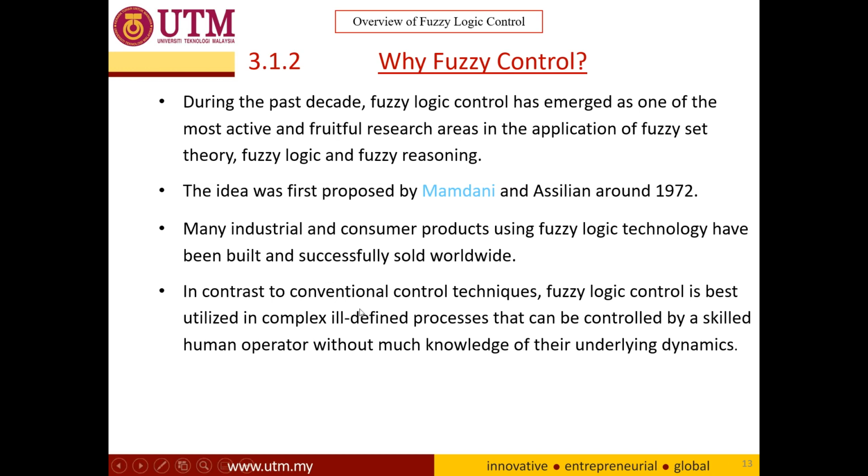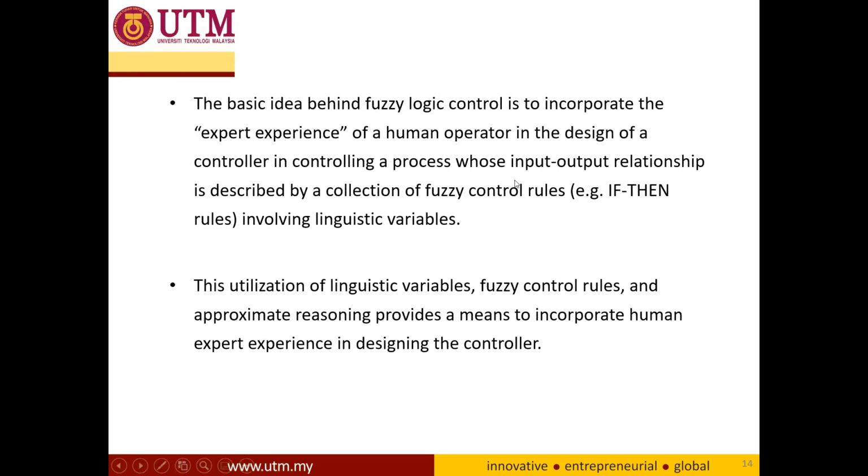In contrast to conventional control techniques, fuzzy logic control is best utilized in complex, ill-defined processes that can be controlled by a skilled human operator without much knowledge of the underlying dynamics. As we will see later, we can include a rule base in the form of linguistic sentences in our fuzzy logic controller. Normally a skilled human operator doesn't really know about the underlying dynamics of our control system, but he or she knows how to control the system effectively. So in our fuzzy logic control system, we can include that mechanism, as we will see later. The basic idea is to incorporate the expert experience of the human operator in the design of a controller